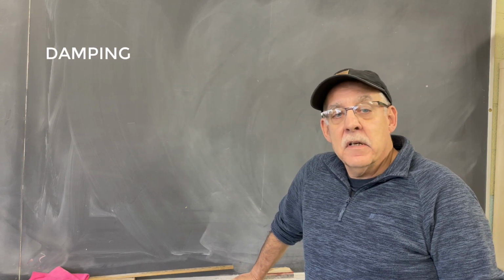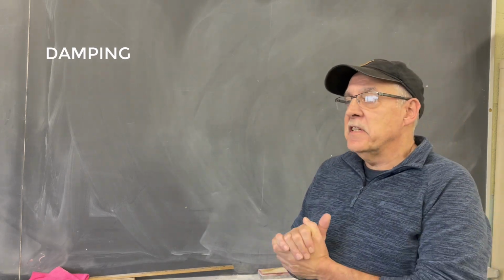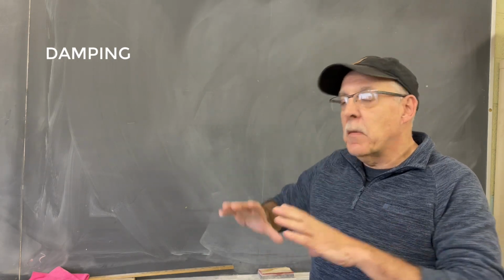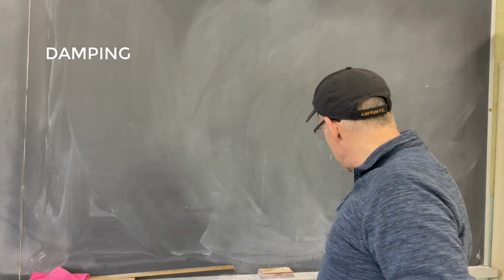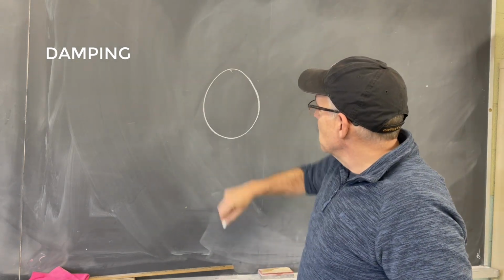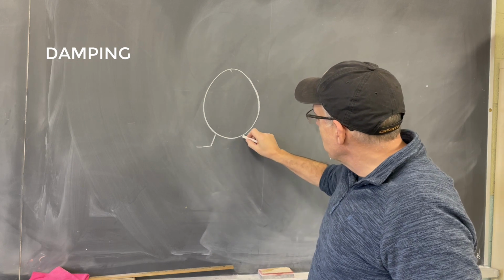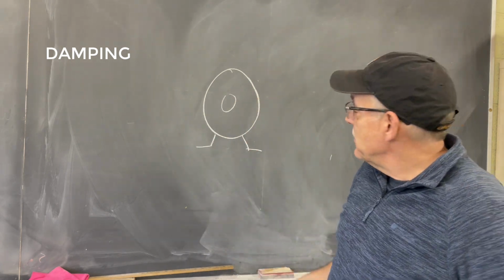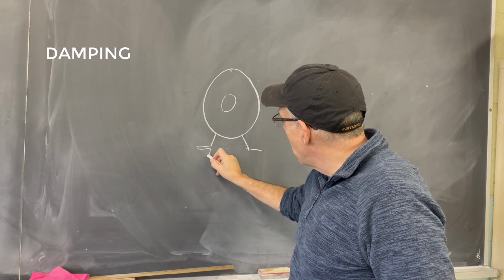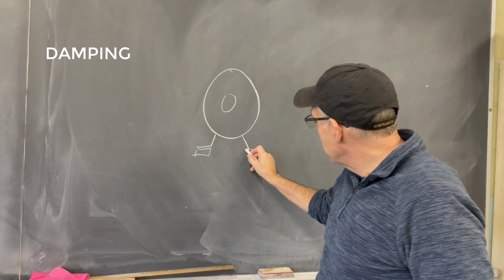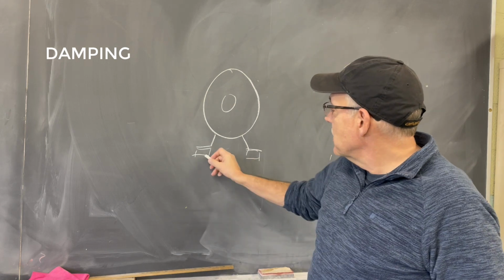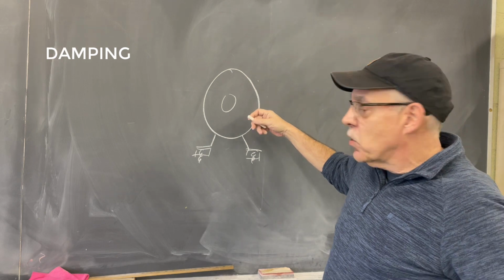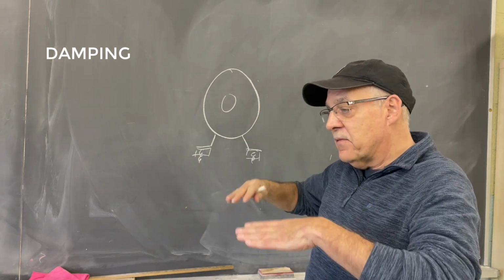Also damping, how something is damped. When we damp something, we're actually isolating that piece of equipment from all the vibration around it. If you're out in the plant and you look at a motor, and we're looking at a motor face on here, here's the drive shaft. If you look underneath the feet of the motor and there's a little rubber pad under there, or sometimes a spring, what they're doing is damping that piece of equipment, damping that vibration out.